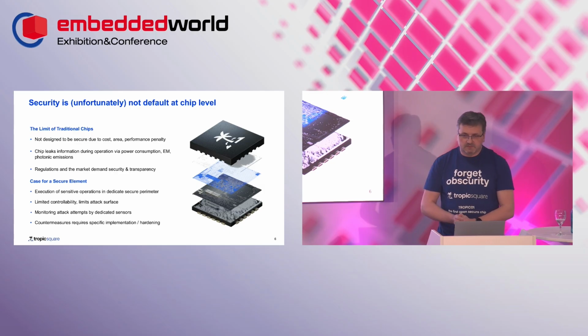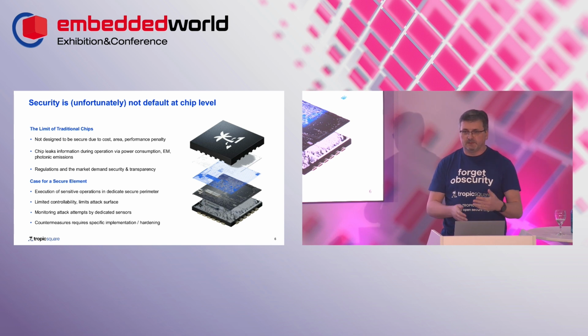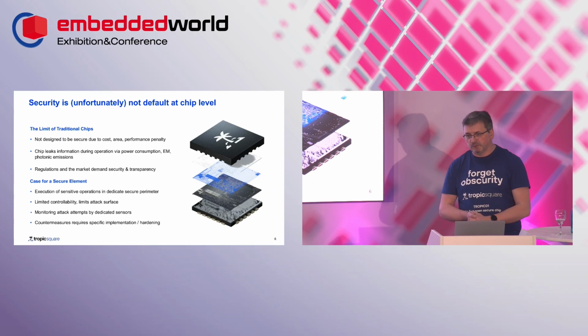So with a traditional chip, if you say, okay, I have a crypto algorithm and I want to implement it, it's easy to do, it will crunch the numbers correctly, it will be fine, but the implementation really leaks data. It's the reality of the transistors switching between zeros and ones, and variabilities in the silicon, so you don't have perfect power traces. And from these power traces, some people can definitely guess what numbers are computed. So even if you keep your keys secure, during computation in an unsecure environment you might be leaking data without knowing it.